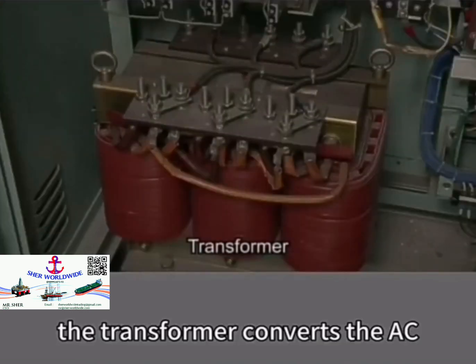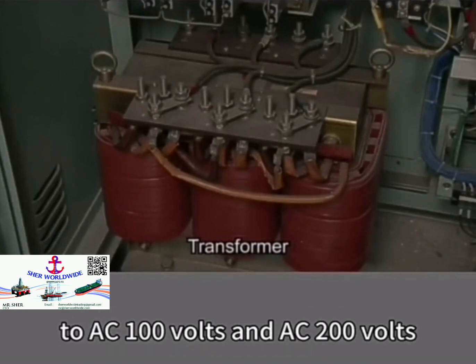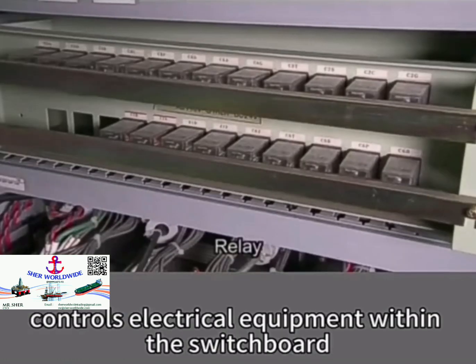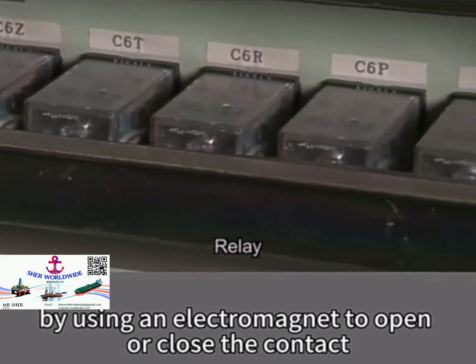The transformer converts the AC 440 volts supplied to the switchboard to AC 100 volts and AC 200 volts, the control voltages for relays and other important parts. The relay controls electrical equipment within the switchboard by using an electromagnet to open or close the contact.